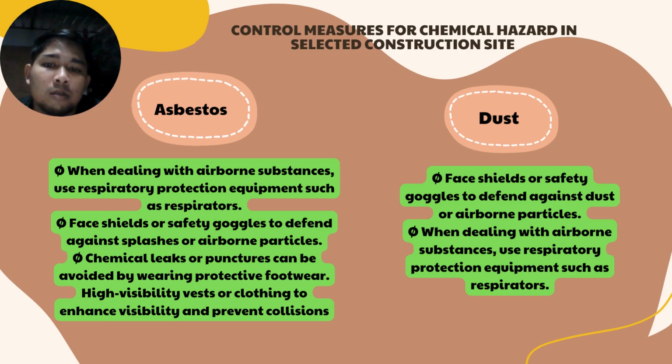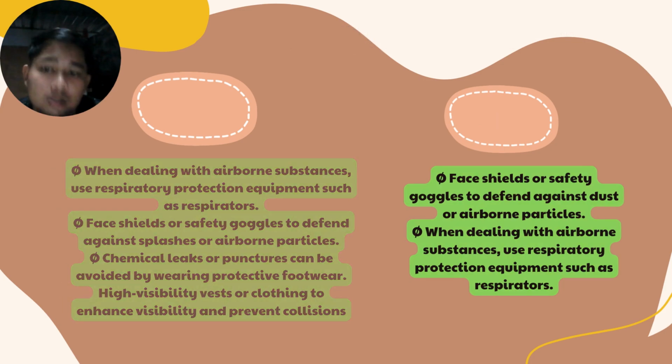Second is dust. For dust, use face shields or safety goggles to defend against dust or airborne particles. When dealing with airborne substances, use respiratory protection equipment such as respirators.